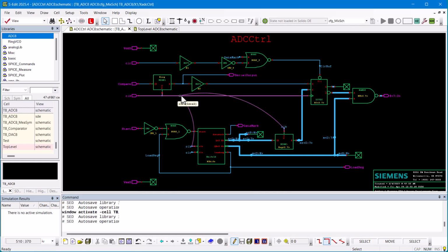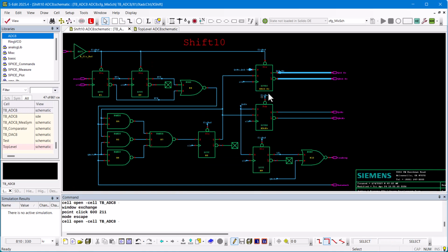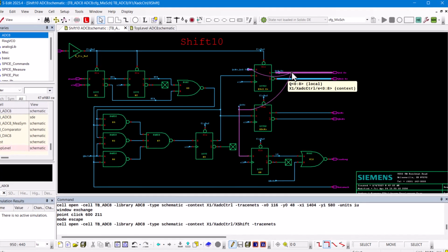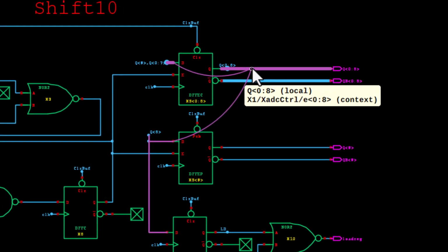For mixed signal designs, which are often packed with buses, net bundles, and their individual bits, tracing connectivity can be tough. That's why Dynamic Info Wire Highlight is so valuable, because it supports both single wires and buses to empower you to quickly track down complex connectivity and understand your design much faster. Here you can see that part of the Q bus goes back to the input of the flip-flop, while the last bit goes down to a different flip-flop.